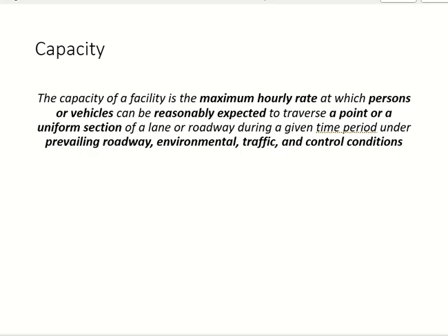Which one depends upon a shorter time period? Flow rate. So this is the critical thing about this definition. If you take the definition of volume, where capacity is maximum volume, then you are ignoring the traffic variation in small time periods. Flow rate covers that.